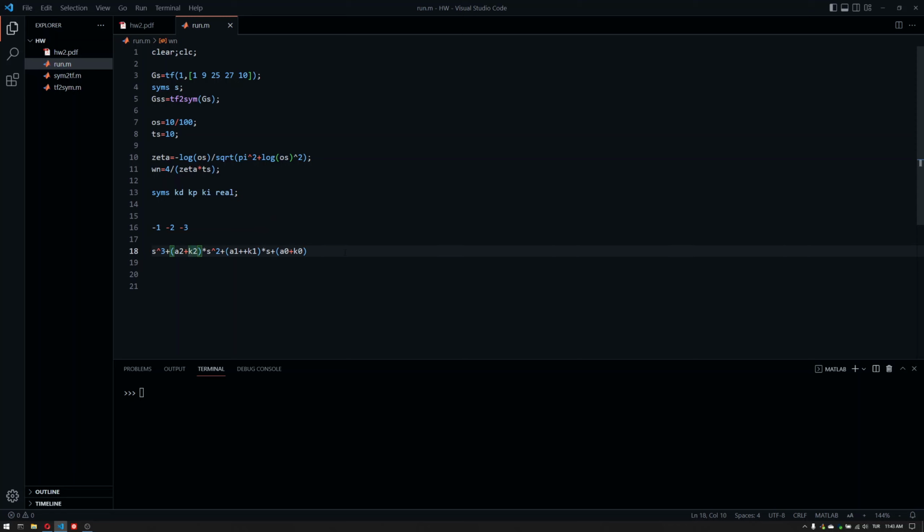If we are missing certain coefficients or certain influence to coefficients, that would translate into the following. We cannot freely assign all the poles of this polynomial. We can only partially assign the poles here. And when we drop down to just one coefficient, then you already know what's going on here.